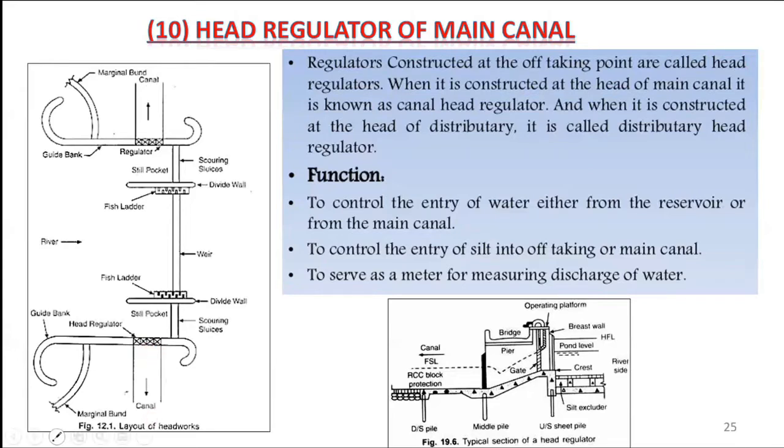If from main canal we are off-taking a branch canal, then here we have to provide a regulator, and that would be called head regulator of the branch canal.